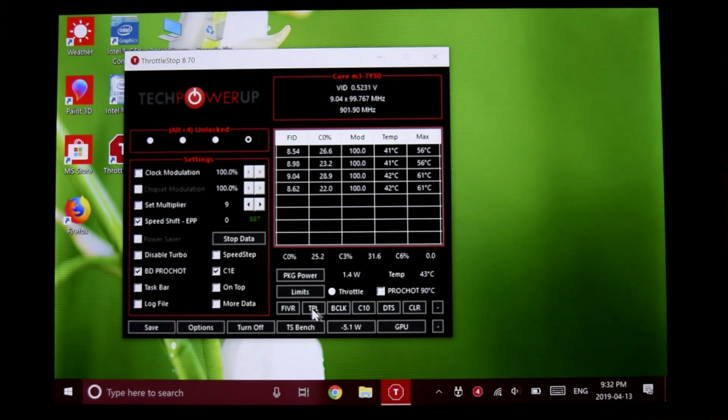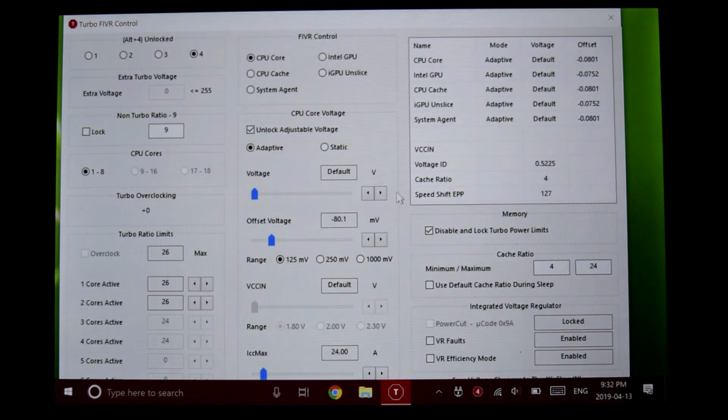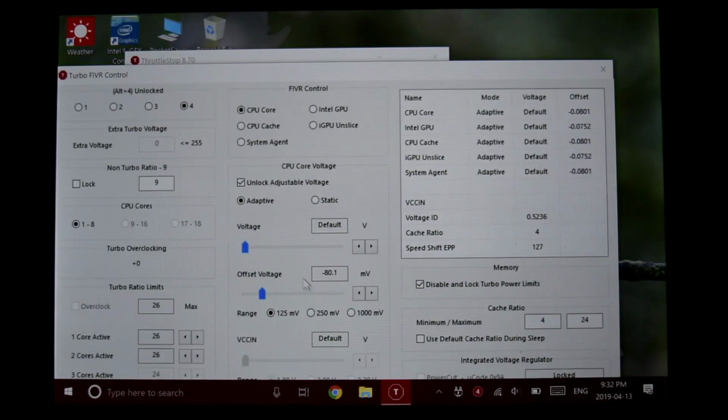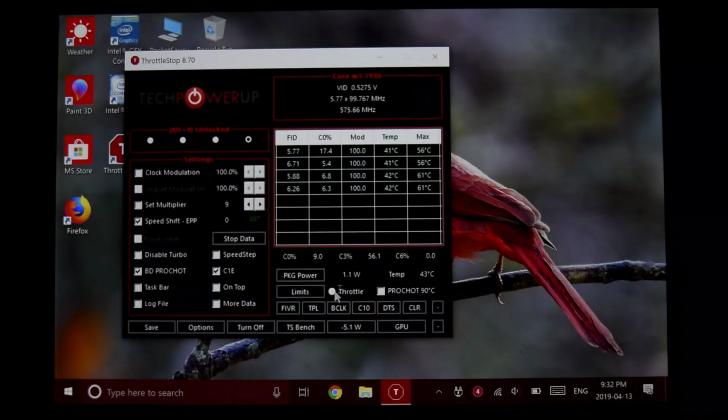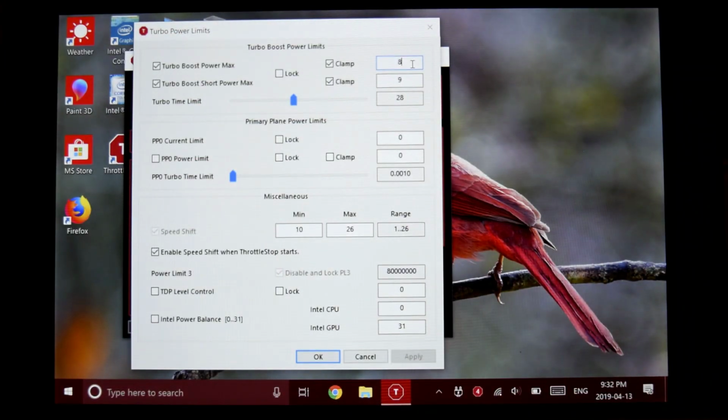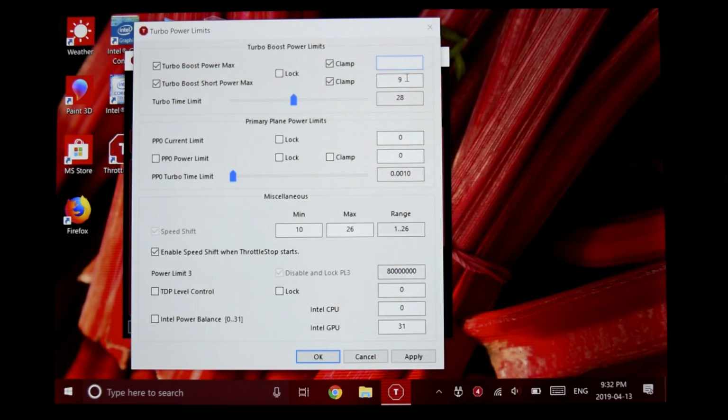Now you can go and unlock the TDP. The undervolts will cause a little bit of improvements in performance, and then increased TDP can go towards mitigating. Even if you want to run something conservative like 5 watts, you're still going to see a massive bump in performance, because it's still half a watt better than what the 4.5 watt limit is initially.